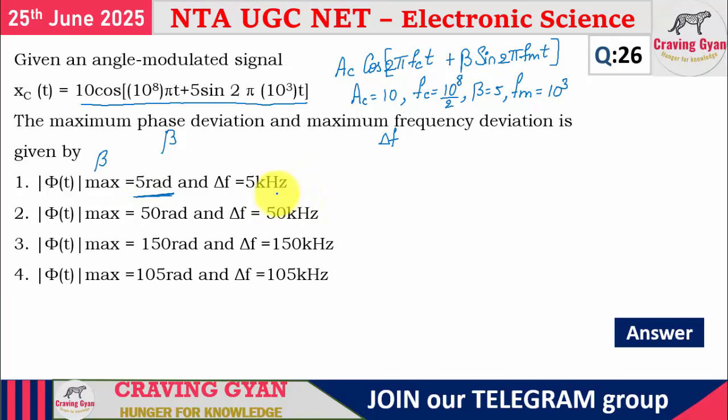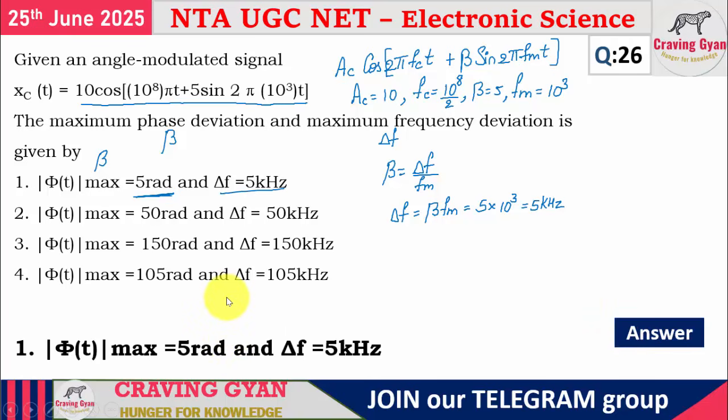And how are we going to define delta f? We know that beta equals delta f divided by fm. Now tell me the value of delta f. How can I rewrite it? It equals beta times fm. The value of beta is 5 and the value of fm is 10 power 3. So the answer will be 5 kilohertz. So delta f equals 5 kilohertz and beta equals 5 radians, and the corresponding option is option 1. For the 26th question, option 1 is correct.